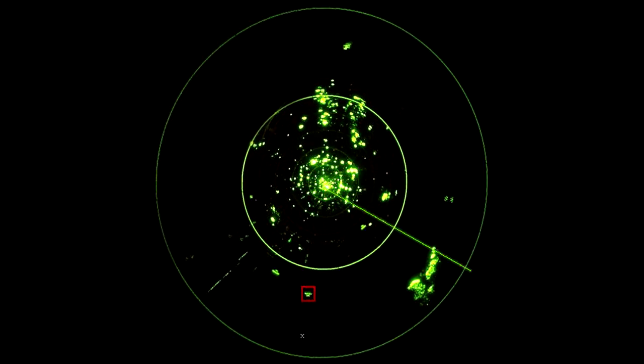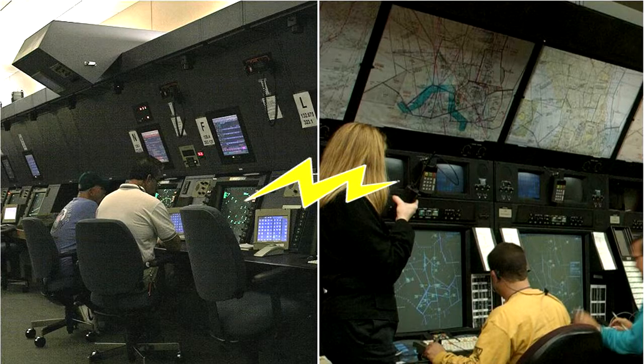The second way is by correlating an observed radar position indication with an aircraft which is known to have just departed, provided that the identification is established within 1 nautical mile from the end of the runway used. The third way is by the transfer of radar identification from one controller to another, under direct communication between the two controllers.